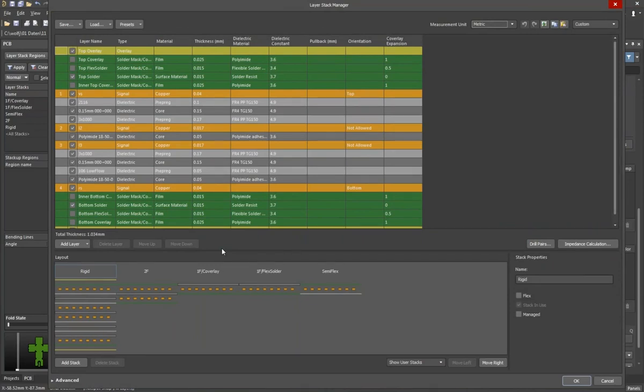I've done this here directly in Altium, so I created this board shape on a mechanical layer and already defined it as a board shape, which you will find up in the point Design, Board Shape, Define from Selected Objects. So what I drew on the mechanical layer, I selected everything and decided this should be my board shape. Based on this board shape, we can switch over into the board planning mode. So by typing number 1 on your keyboard, you can change to the board shape.